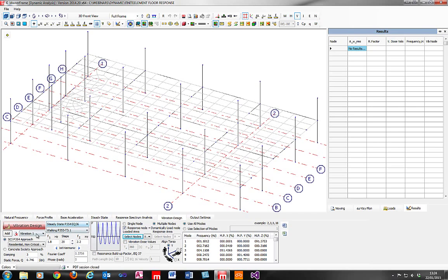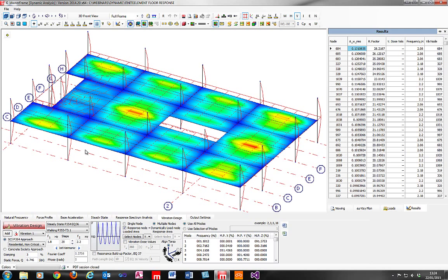So let's action now our first vibration design case. Another little point to note is that we are interested in the response factor due to someone standing on the floor, not lying down in any one of these directions, but standing on the floor. So their torso is vertically aligned to our y-axis. And we've established here with these nice color-coded regions that we have a hotspot of response factor occurring around this location here. And we have the values of the RMS acceleration, which very conveniently gets converted into a response factor at that location.